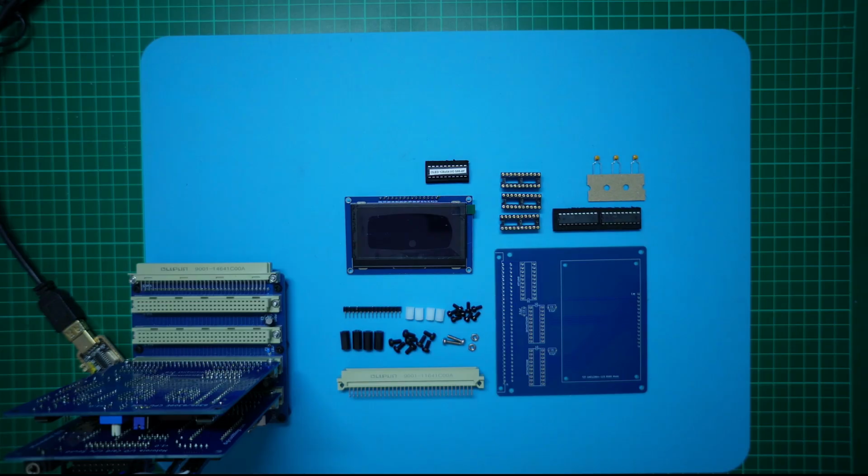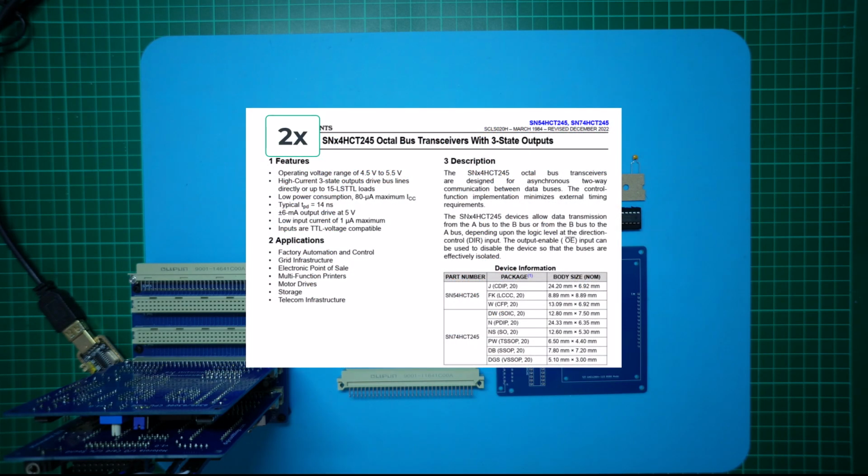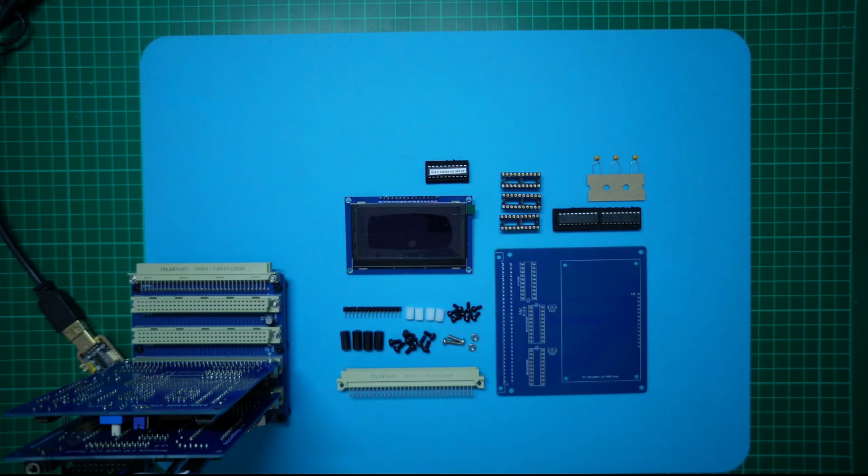So, as I thought it was more maker-friendly to just use two 74HCT245 bidirectional buffer chips instead of two different chips, I redesigned again for version 1.2. So here we are at the third and final version of this seemingly simple project.